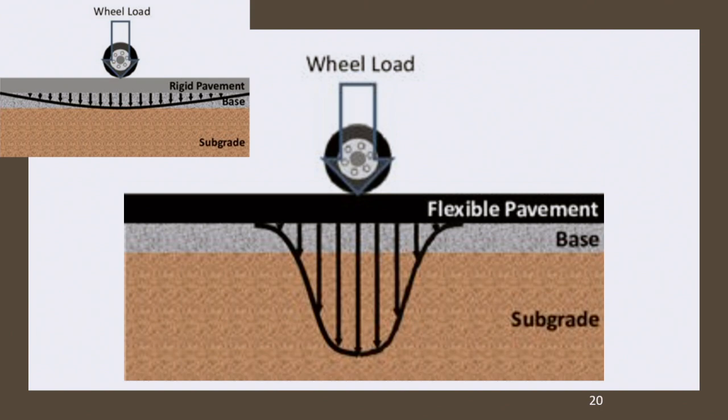So I'm not sure, did you have similar specs here in Nigeria where you have a minimum percentage? Like, what do you require the contractors to do when it comes to the compaction? Is it 100%, 98, 95? 100? Okay. So it's always safer to require higher compaction. You can never guarantee what's going to happen down the road, especially with all the increase in the number of vehicles and the loading per vehicle.